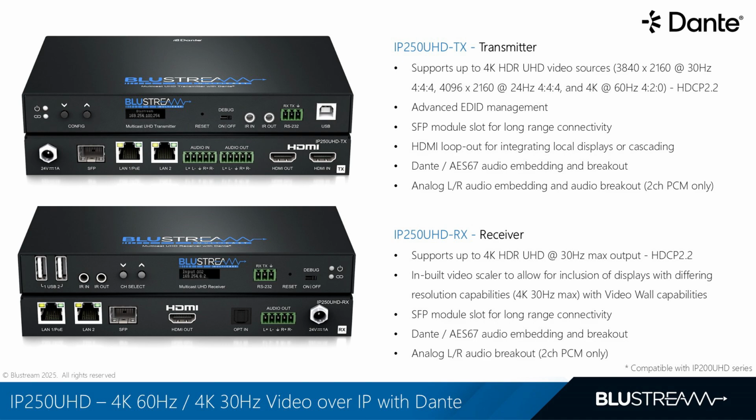Now, these are incredibly useful for installers. You can isolate Dante traffic from video over IP streams on separate networks, perfect for larger systems with dedicated VLANs or security requirements. Or, if needed, both Dante and video traffic can share the same copper or fiber uplink, thanks to the flexibility of the first LAN or SFP port.